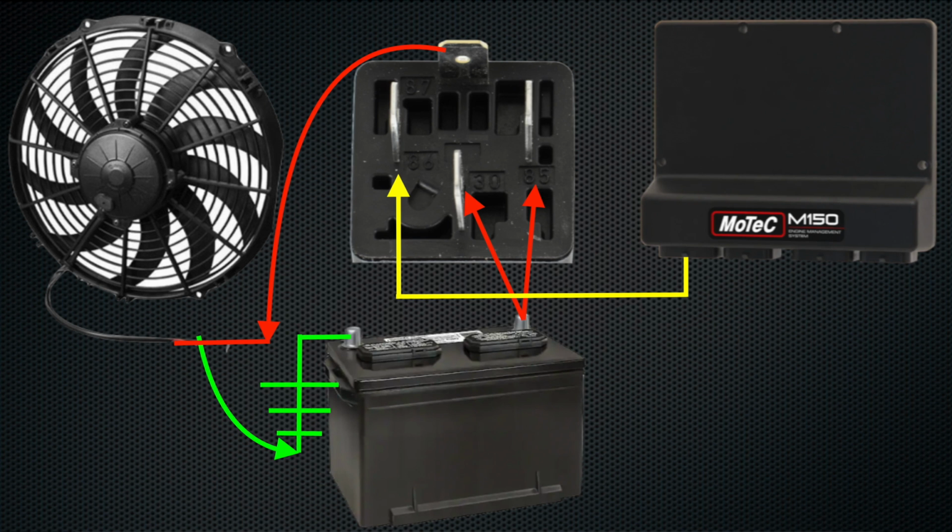We can see that the relay has numbers associated to it. Looking at the bottom of the relay, you'll find that there's an 87, a 30, an 86, and an 85. Those are the numbers you'll find on a standard relay. 87 would be the output from the relay, and that's going to send the 12 volt to the fan to turn that circuit on. 30 is going to be typically fed from our battery power source, so 12 volt in. So it comes into 30, comes out 87.